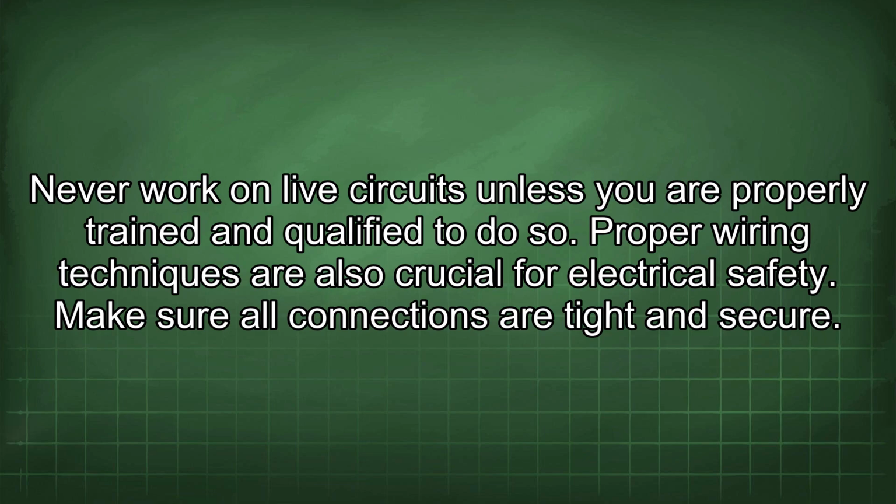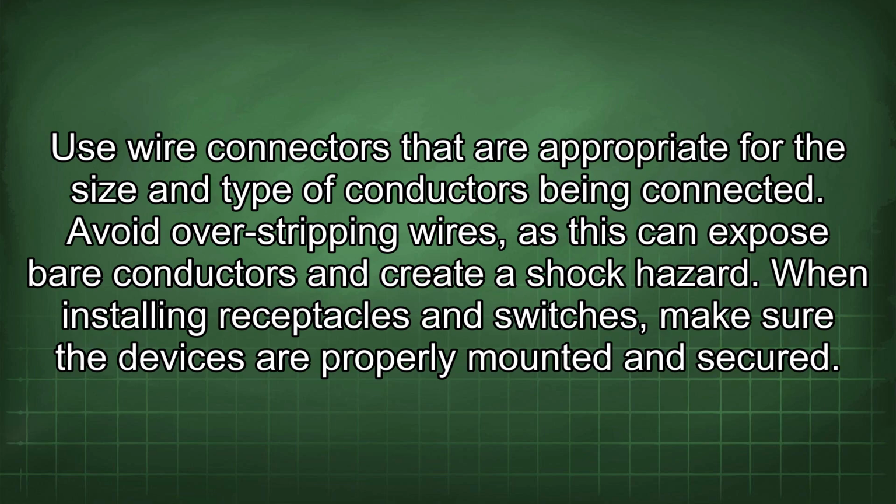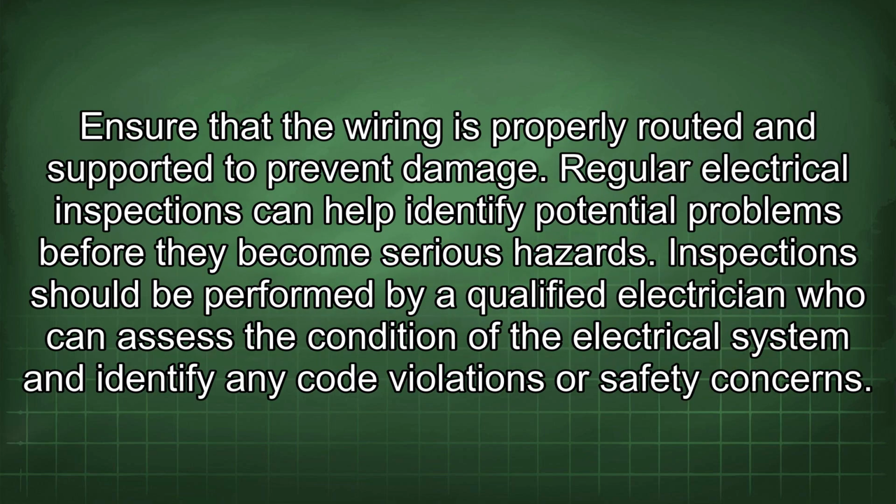Proper wiring techniques are also crucial for electrical safety. Make sure all connections are tight and secure. Use wire connectors that are appropriate for the size and type of conductors being connected. Avoid overstripping wires, as this can expose bare conductors and create a shock hazard. When installing receptacles and switches, make sure the devices are properly mounted and secured. Ensure that the wiring is properly routed and supported to prevent damage.